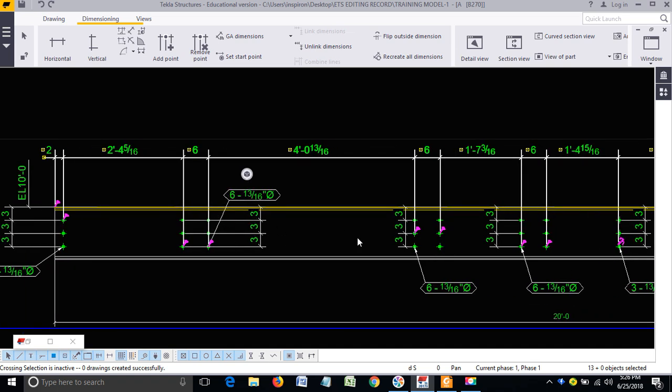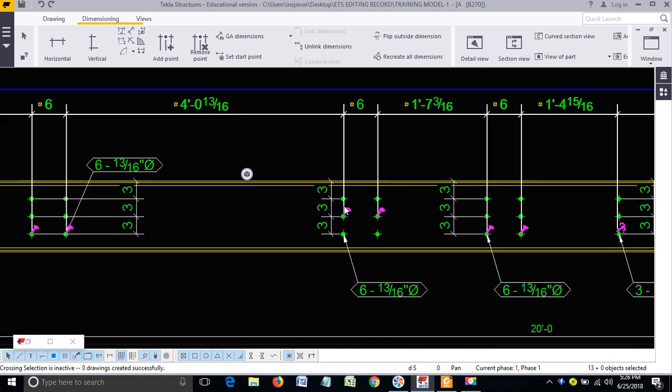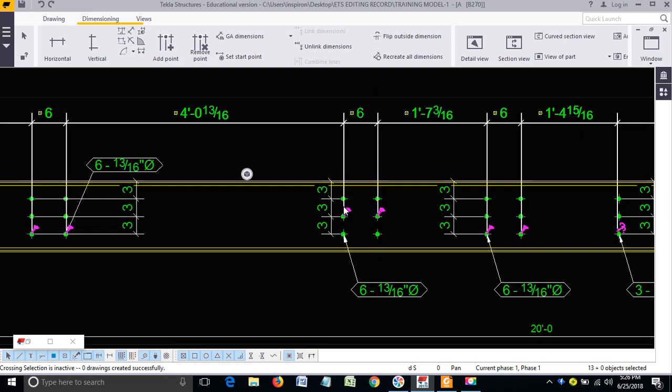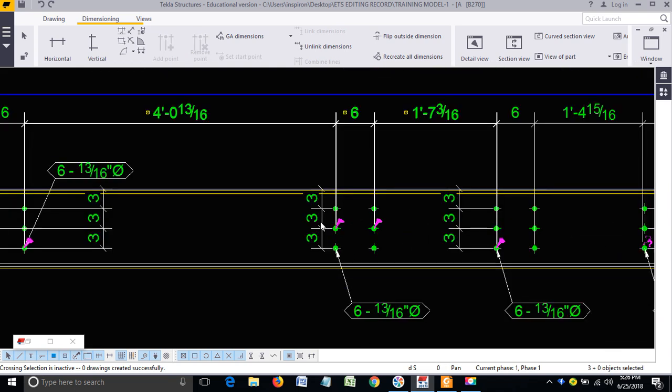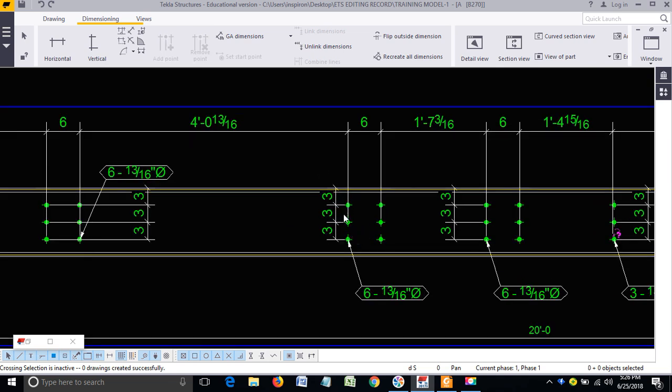Next come to here. This is fine. If you come to here, he picked from the second hole onward. See here, he didn't pick from the bottom of the hole. This dimension will be applicable for these 4 bolts only, not these 2. Clear? Okay. Then vertical also, the dimension he gave is only applicable for these 3 holes only, not relevant to these 3 holes.